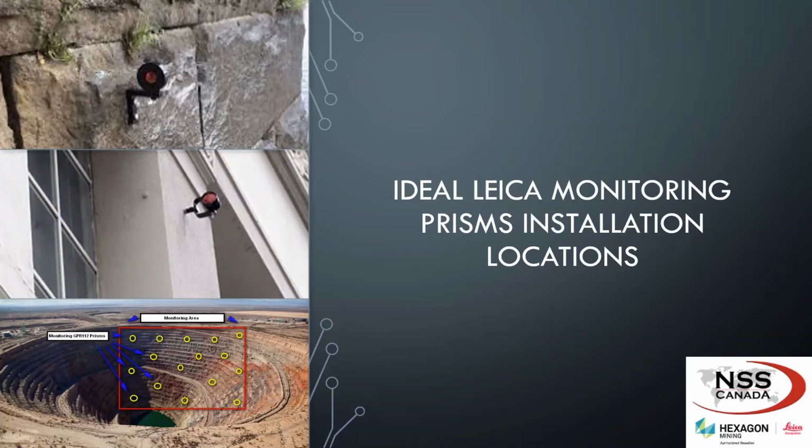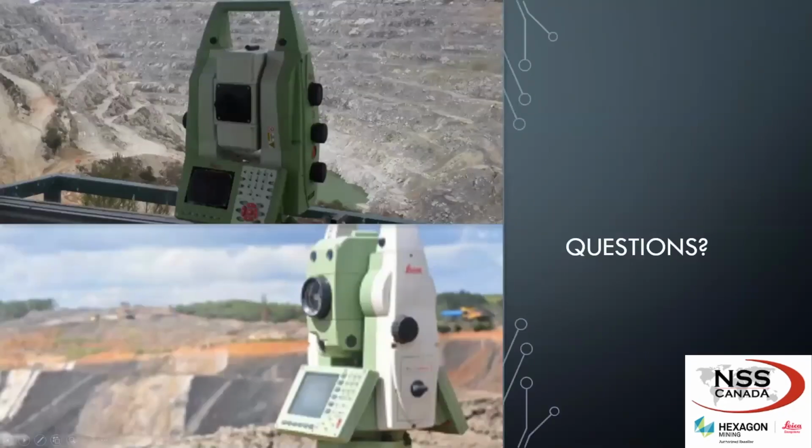The Leica monitoring prisms do not have to be GPS surveyed in. These prisms are located using the Leica GeoMoS monitor software. So these prisms are not GPS'd in. They are actually shot in after we do our reference. We do our orientation with the gun. Remember I was talking about the learn. We press the learn, we learn where this is. Bam. And that's it. Any questions?